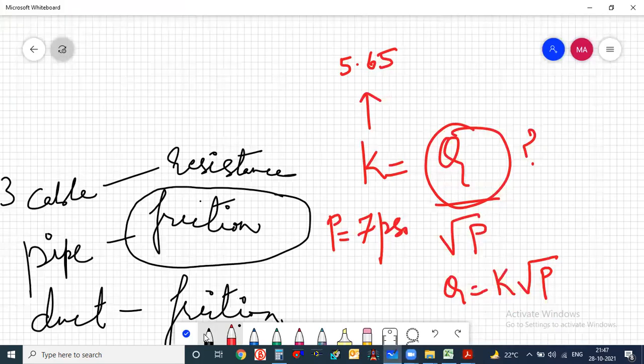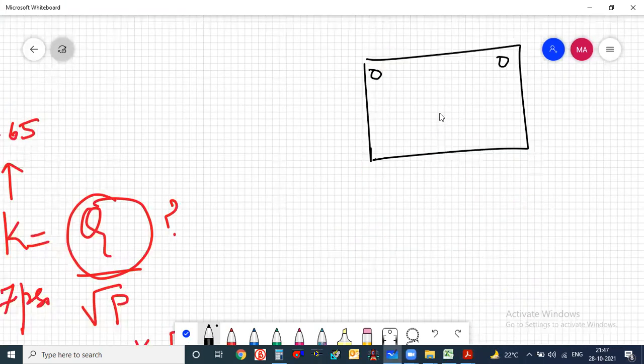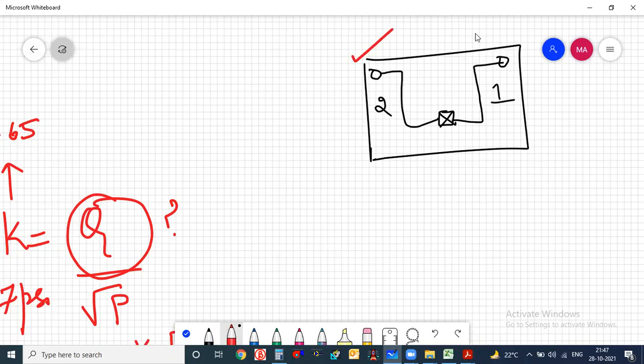Suppose this is your building, for example. One sprinkler here, one sprinkler here, and your riser shaft is coming from here, for example. Now the sprinklers are going here, sprinklers are going here. You are confused. You don't know which is the longest path. So what we have to do, we have to submit 2 reports. One report this, one report this. So the approving agency will check both the calculation results, and they will approve. They will tell, okay, you can go ahead with this calculation.